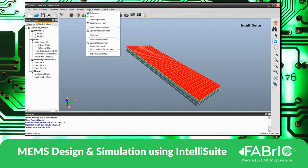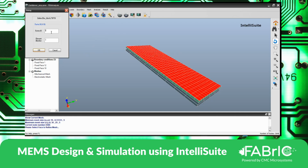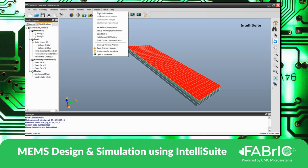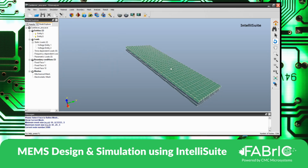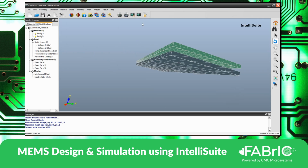Now, we all please remember that we are trying to do an electrostatic force-based simulation where, due to the electrostatic force, there is a deformation in the geometry. So whenever we are applying electrostatic force, it is recommended to use a modify electrical mesh. So I click on geometry. I would say that this has to be split by 2, and then each element will be split by 2, and then we update the electrical mesh. So now the electrical mesh is applied,